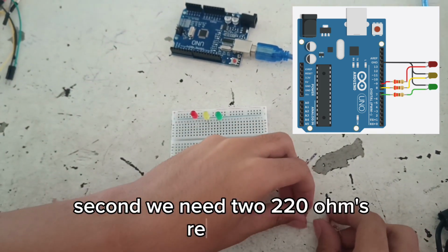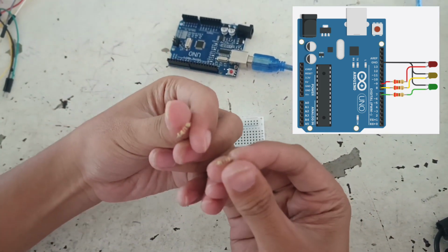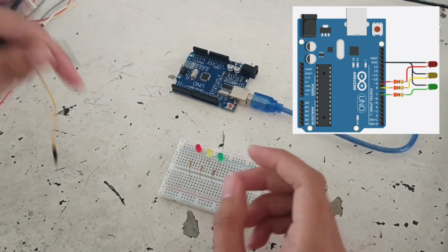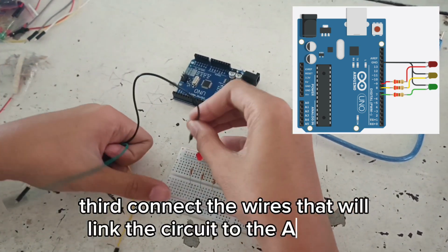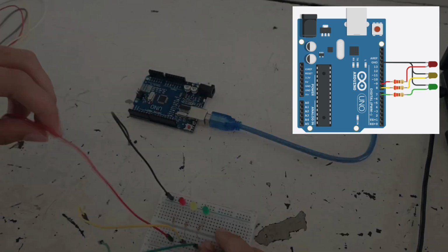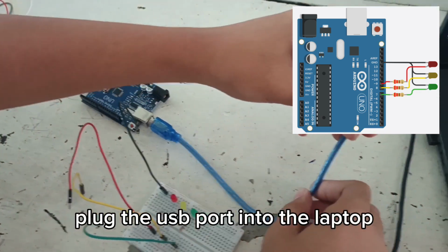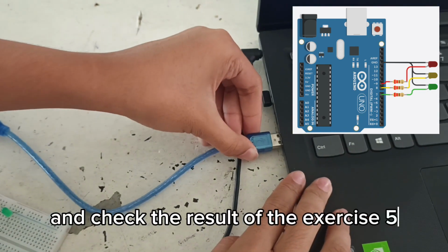Second, we need 220 ohms resistor and connect it to the anode terminal of each LED. Third, connect the wires that will link the circuit to the Arduino. Finally, plug the USB port into the laptop and check the result of the exercise 5.